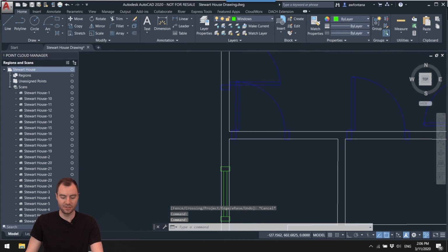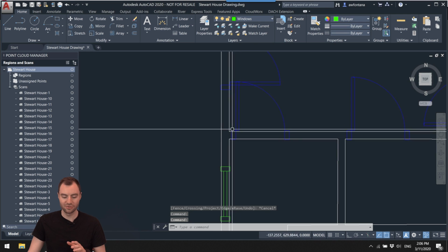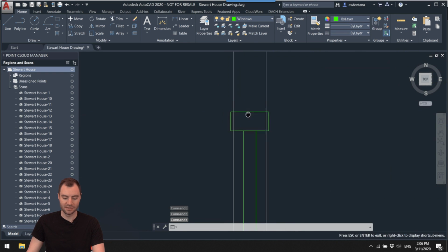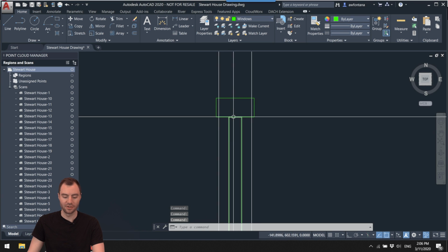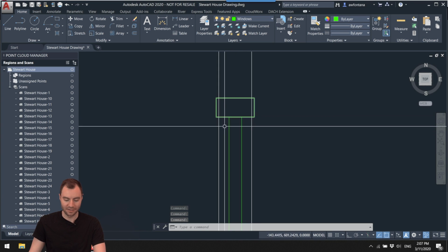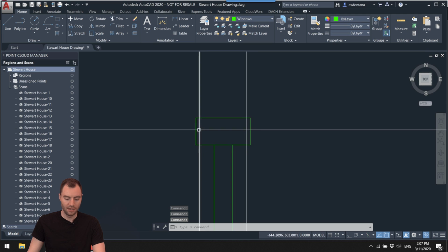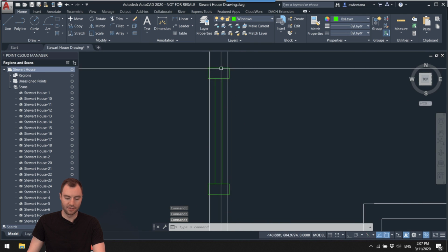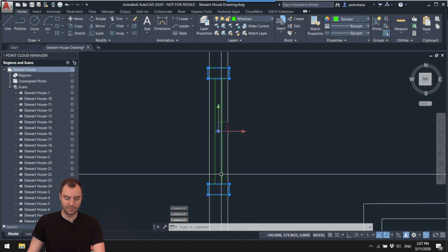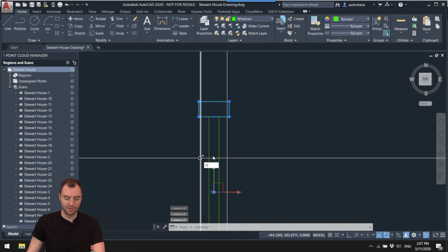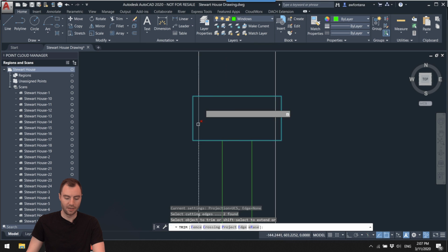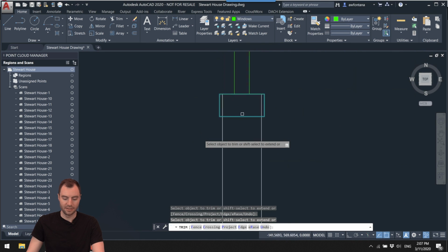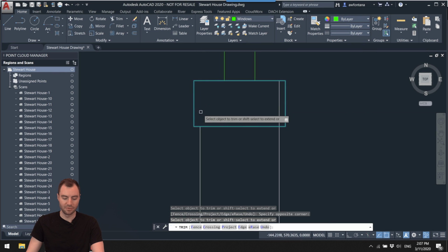You have to do something a little bit different to trim inside of blocks using blocks. That's why it was a little bit advantageous to not turn the windows into blocks, because now I can use the windows to trim. And you can cut the walls out from inside the block and in between.